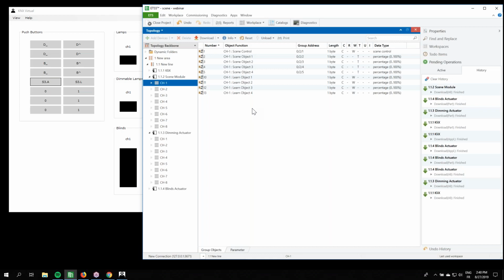If I just dim up the lamp to a specific value, then when I stop the dimming, I have reached the dimming value that I want, let's say, as user of the function. Then the device will via a feedback object send me that value that has been reached, so to say. So that is a reaction of the device. Okay, just let me show that to you.